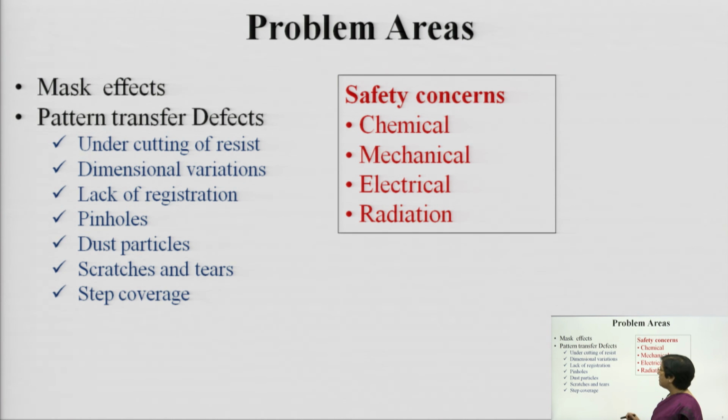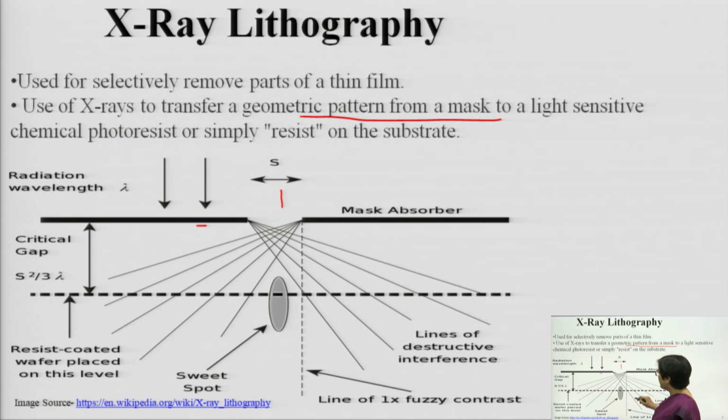Okay. So you have plus and minus points. The plus point is that it is moderately expensive and a faster process as compared to e-beam lithography, but the disadvantage is you have to take care of the repositioning of the mask, and another thing is X-rays are harmful.